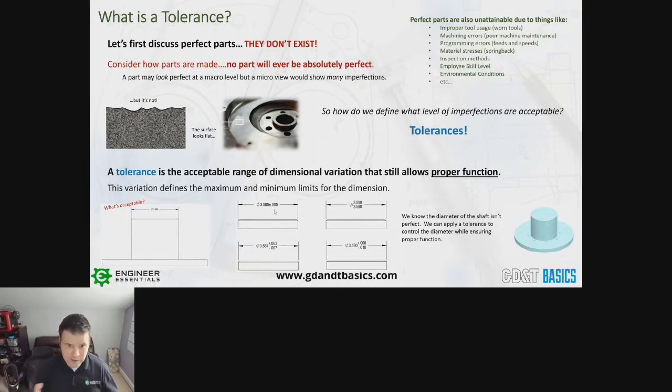There is no difference. Sometimes companies specify, not to get off on too much of a tangent here, that you have to do limit dimensions like this so that you know the absolute limits for inspection. Some, especially production facilities and machinists, love when you put it in plus or minus something, right, dead nominal, because a machinist is going to be targeting 3.585 every single time. And they're going to hope that they get it dead on as close as they can. And then you have other variations that your company may or may not use. Some are due to statistical tolerance control. Some are due to single side limits, which are another reason people put these types of tolerances on.